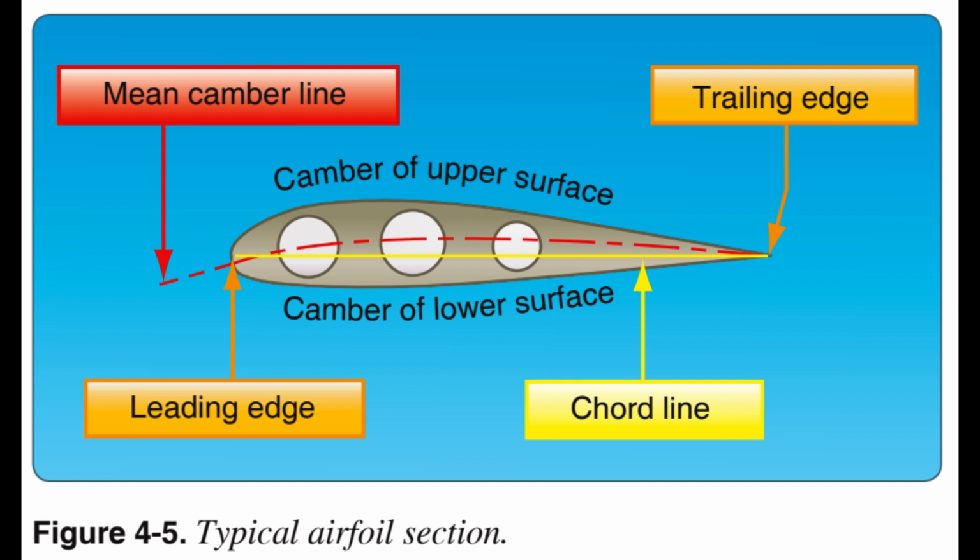If a wing is constructed in such form that it causes a lift force greater than the weight of the aircraft, it will fly. If all the lift required were obtained merely from the deflection of air by the lower surface of the wing, an aircraft would only need a flat wing like a kite. However, the balance of the lift needed to support the aircraft comes from the flow of air above the wing. Herein lies the key to flight.